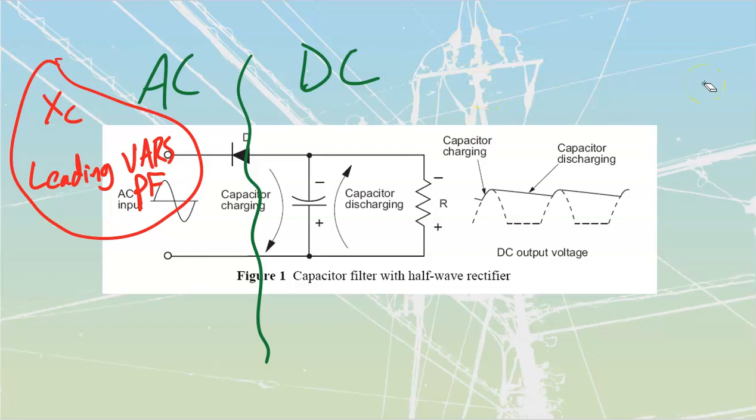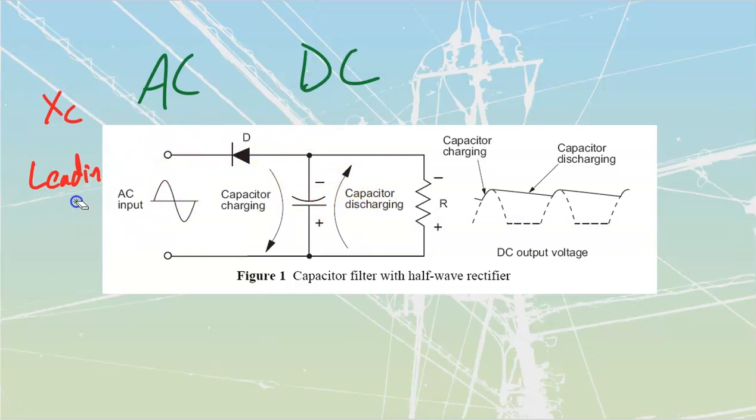Okay, looking at this one over here, what's going to happen on the DC side, and I'll remove that big nasty line there in a second, is that we're going to charge up this cap, and then this cap is going to be able to discharge based upon wherever the greater amount of volts are going to be inside the circuit, either from the AC input that's going to come through the rectification or from the cap itself. So let me just erase all of this so that we can see what's going on again.